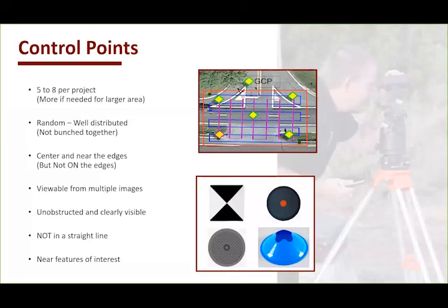What ground control points are can be physical features on the roadway, maybe like manhole covers, storm drains, or things that you interject into the scene, otherwise designed for aerial targets, so like checkerboards, or mats that have high contrasting colors, or even, in one of the courses I went through, soccer cones that you can place. You place them randomly throughout your scene.